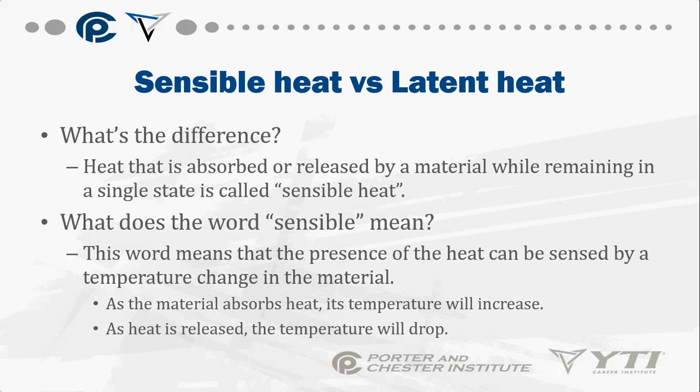It wouldn't change temperature at 212 degrees at that instant. It would just change state. That's latent heat. Or for simpler terms, it's pretty much what we consider hidden heat. Heat that our body really doesn't feel or sense in any sort of way.